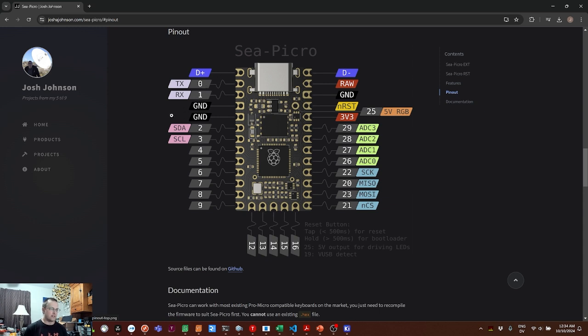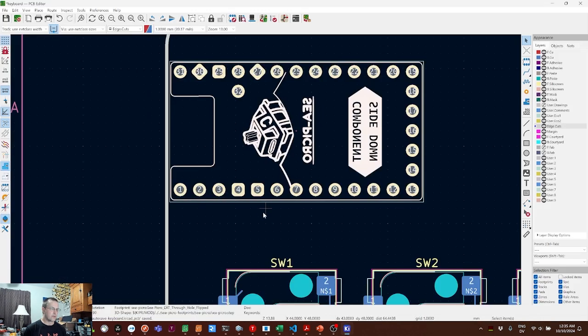So we want to wire our columns and rows to 8 of the GPIO pins. And the ones I like are right here, because there's 8 of them. So we could use 2, 3, 4, 5, 6, 7, 8, 9. We don't care about any of the other capabilities of these pins. I'm just picking these because they're on this side. Again, though, remember we need these names for the pads. So after our 2 square ground pins, we're going to start numbering with 2 through 9.